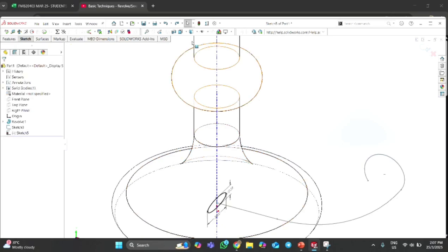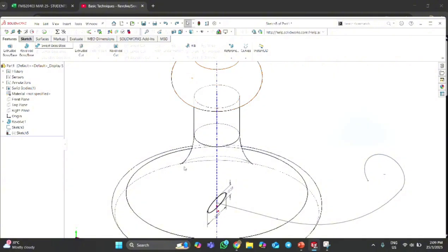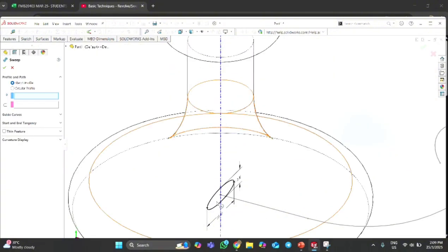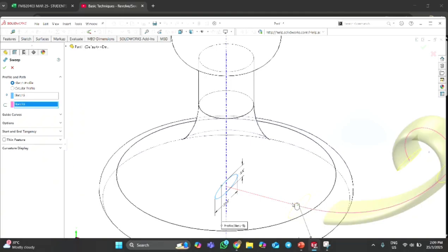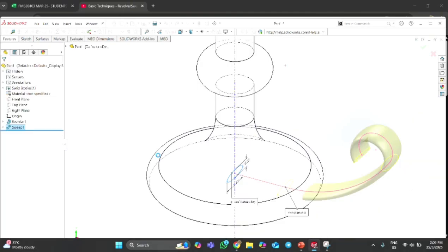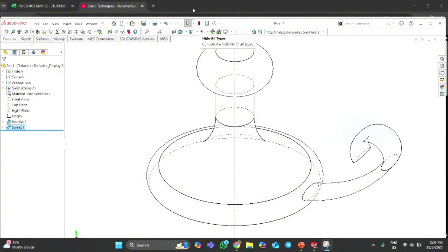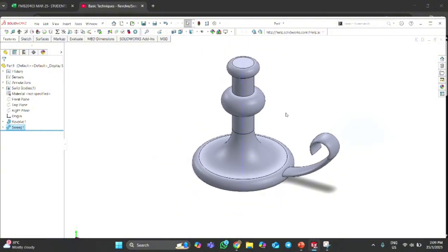So we're going to bring the ellipse to the bottom. So press from this point to this point and press coincidence. Now we're going to use the sweep boss feature and click this ellipse and this line. So the outcome will be like this. Now we're going to change it to normal, and we're going to get rid of the axis line.